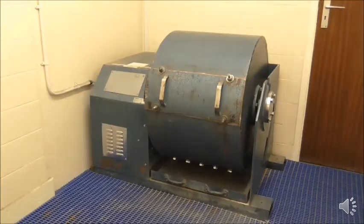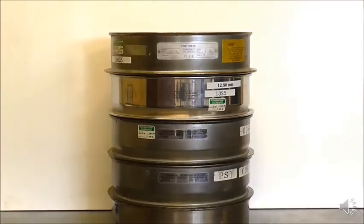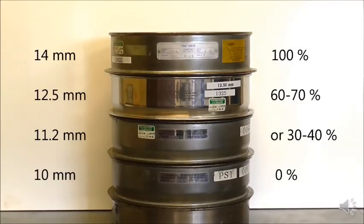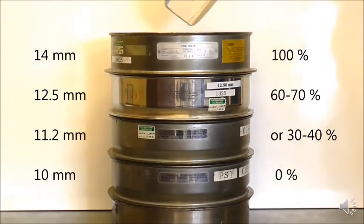They've shaken it, or they've washed away all of the smaller particles, and then they've placed it in that drum with the 12 balls. So here they are preparing the sample. You've got a sample that's being delivered to the lab. It's a bag of about 15 kilos of the aggregate. And you do the sieve test.